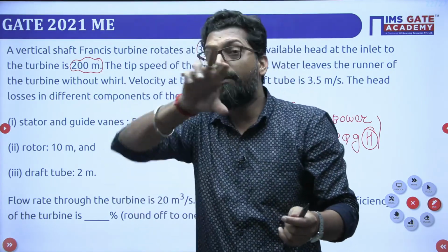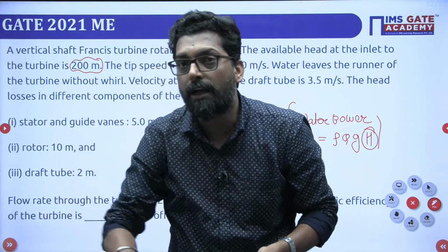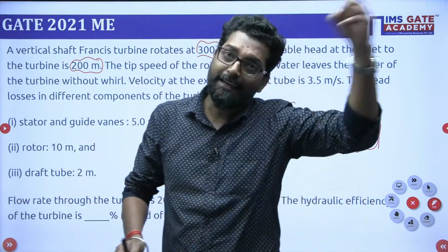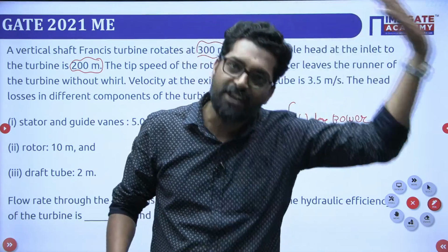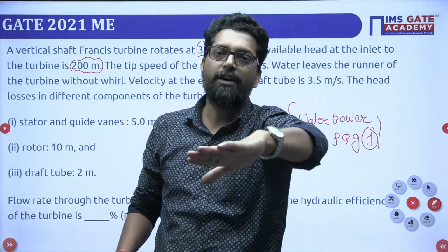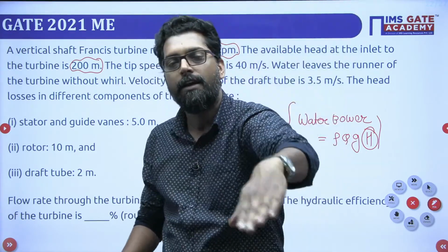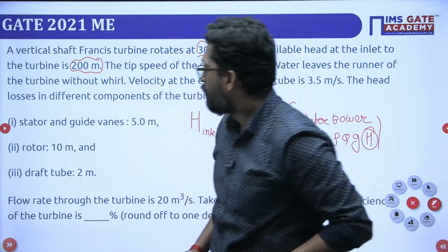In the case of a reaction turbine, a Francis turbine, we cannot use a nozzle. A spiral casing acts as a nozzle. But in the case of a Pelton turbine, we must add an extra nozzle. That means there is an external part. But in the case of the reaction turbine, the part of the turbine is itself a nozzle that plays the role of casing. Clear?